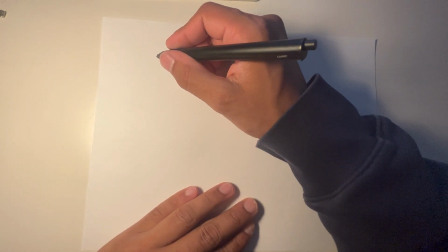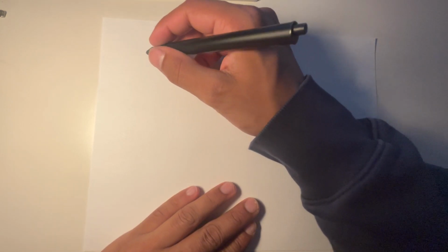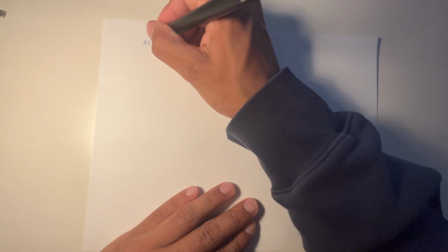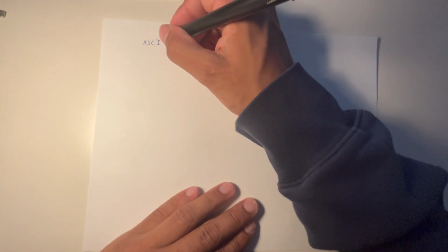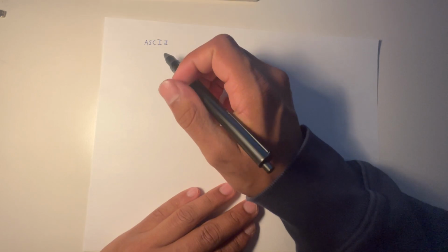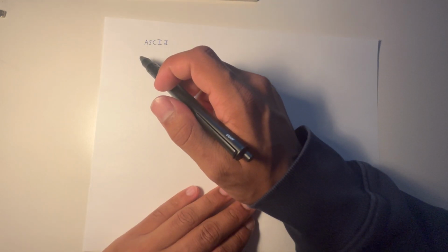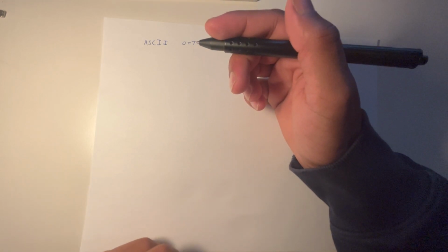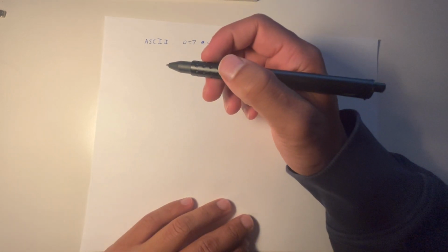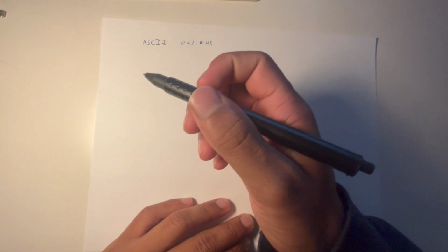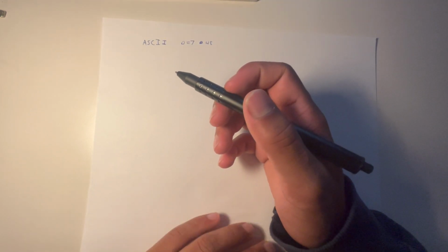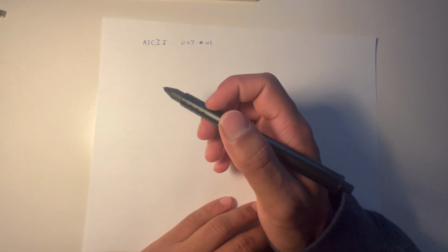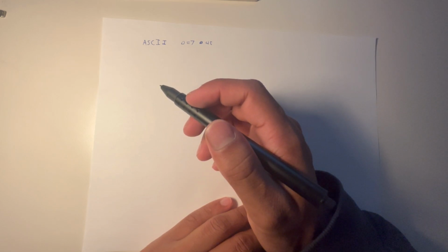So in assembly language, in order to send any information over the serial monitor, it has to be sent as a stream of ASCII characters. ASCII stands for the American Standard Code for Information Interchange, basically just a mapping of values to characters. So the question becomes, in assembly language, how do we convert a binary number into its several decimal characters? The answer, or at least one answer, which is what we used in this project, is to convert the number to BCD, or binary coded decimal, first.